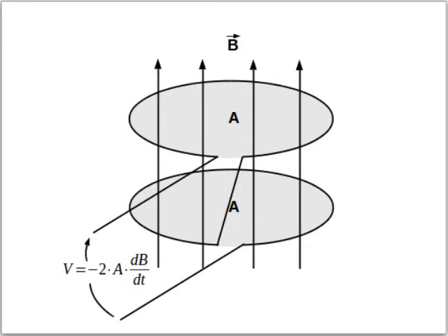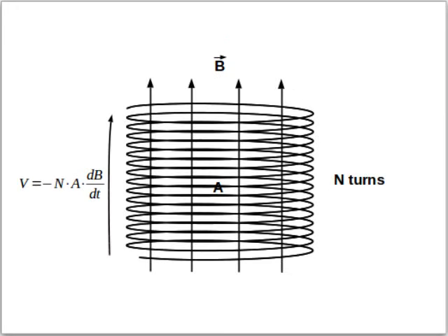If you wind two separate loops of wire around the perimeter of two flat, identical areas and make all the lines of magnetic field cross both, any change of the magnetic field with time will induce the same voltage on them. If you connect these loops in series, the resulting voltage will be double. It is easy to deduce that with n loops in series you will have n times the voltage of one loop.